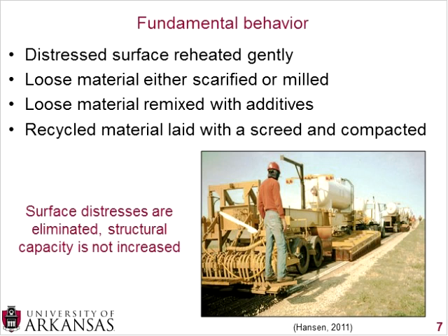And when you do reheat that, then you want to loosen the material. And like I said, you can either scarify it, which is in the picture below. Literally, there are little hinges down there that are scraping the pavement and mixing the very top layer, getting that very highly oxidized, very thin layer on top mixed in with the unoxidized layers anywhere from 1 to 2 to even 3 inches below there. Mix that up a little bit.